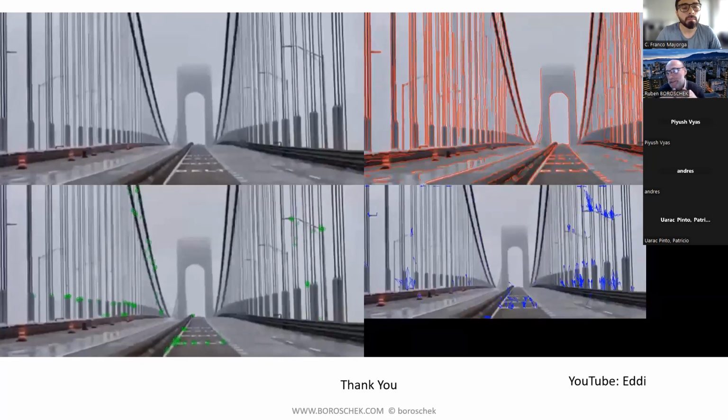So at least we know the influence at the ground level of the rocking components and the transverse horizontal displacement. If we are looking for mode shapes, we know the contribution of that component. And the rotation component is also critical for very tall structures. When you have a small rotation in an 85-meter tall windmill, you get a lot of deformation at the top as a rigid component.